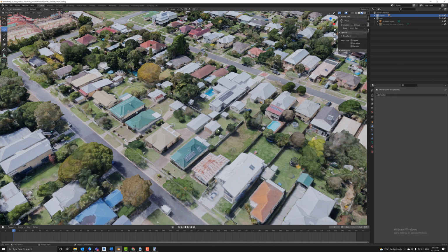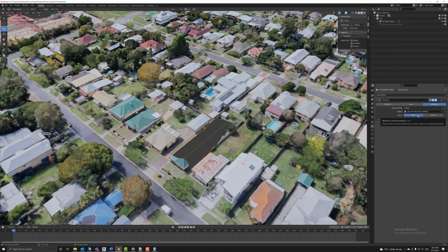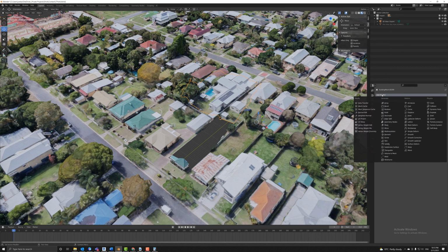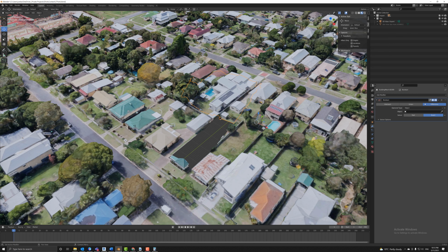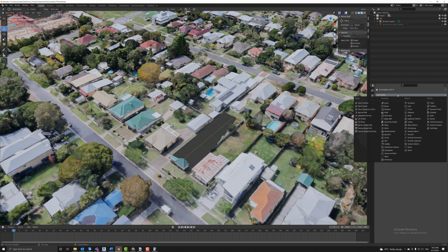Now I'm going to have to select the individual areas of geometry there. I go to add, it's the little spanner looking tool there, and then add a Boolean, and I'll then select the site hole and hit subtract, and you kind of have to do this for every one. So you'll go add modifier, Boolean, click on the little eyedropper, and then I'll just pick site hole from the list.